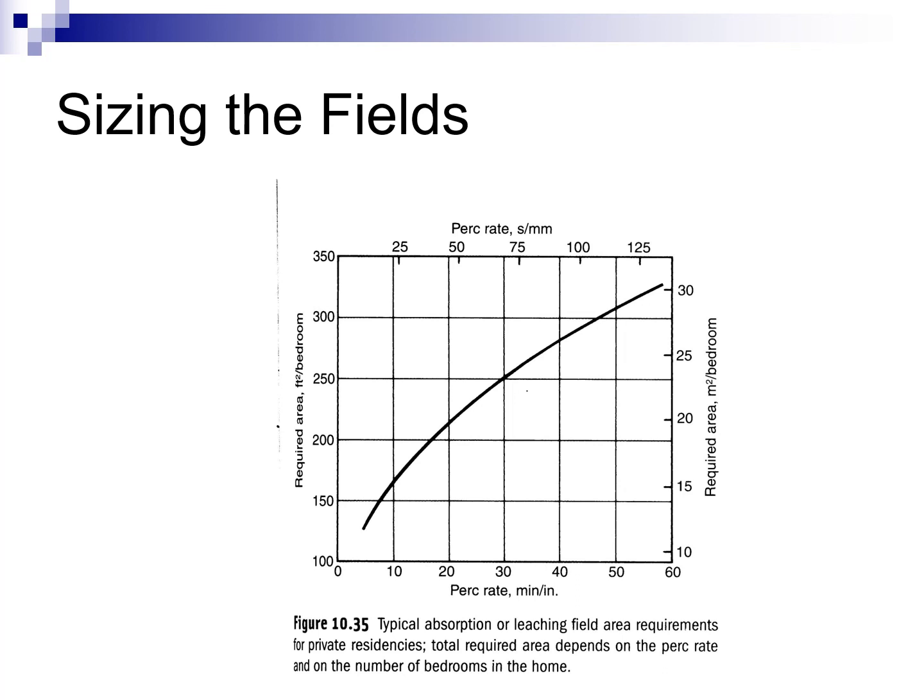So the population has more to do with the amount of water I'm using than the actual number of bathrooms, right? Because if I have 3 people living in a house, I am cooking for 3 people, I'm washing for 3 people, 3 people are taking showers and baths or whatever. But if that house has 4 bathrooms for some reason, I'm still only using water for 3 people in general. So that's why that's done by bedroom and not by the number of bathrooms.